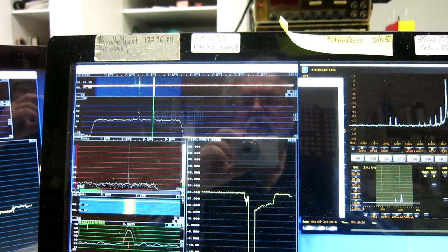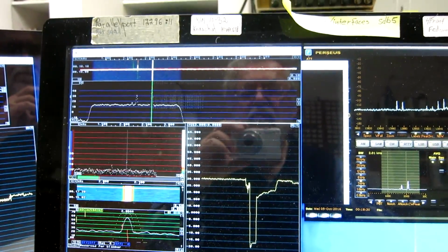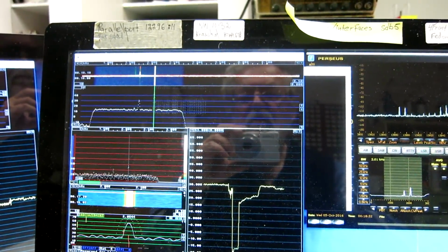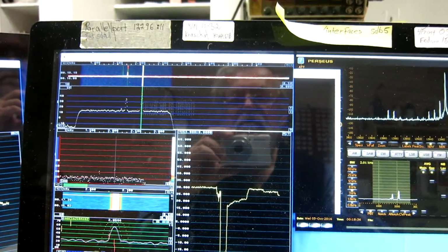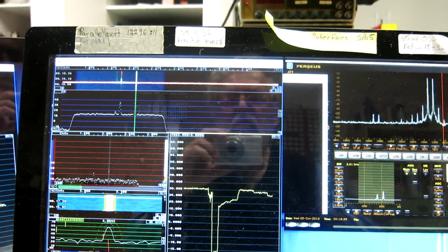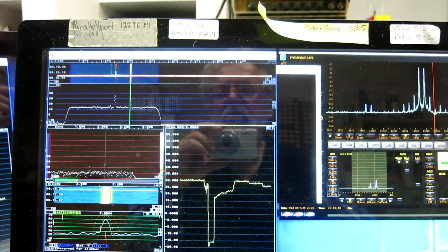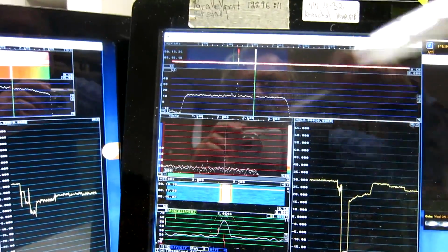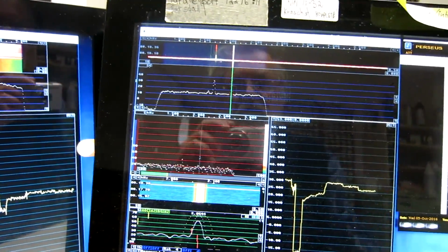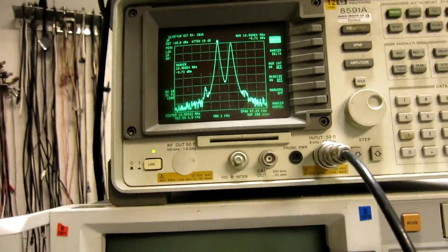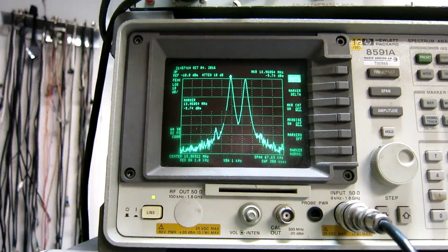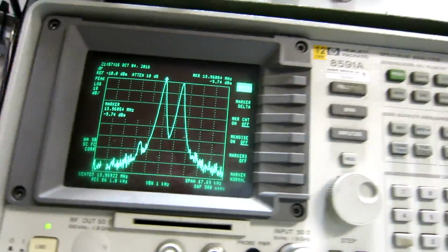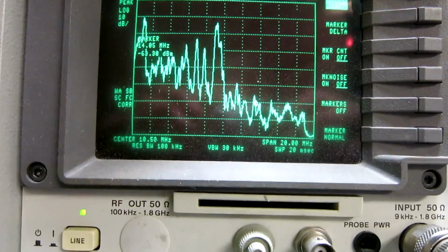There is a significant delay through the processing here. So here is the point of 3 dB degradation due to this third order intermodulation. And the signal level here is -9 dBm. That is a big difference.